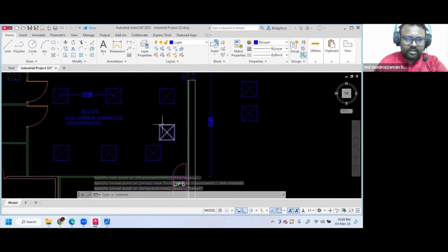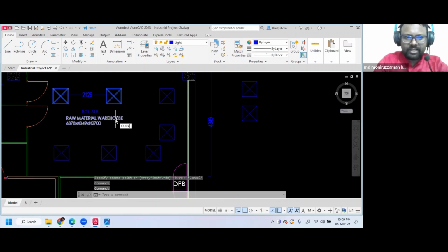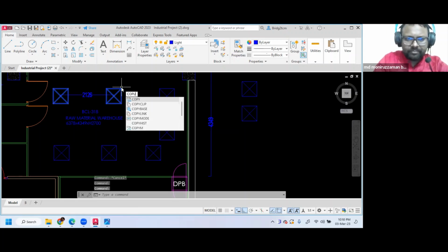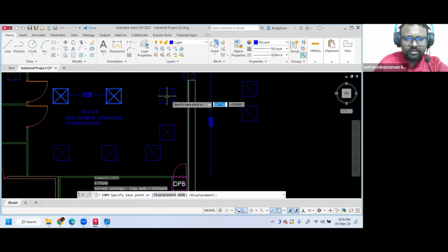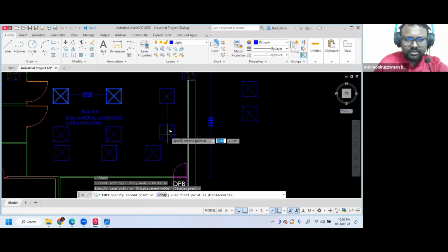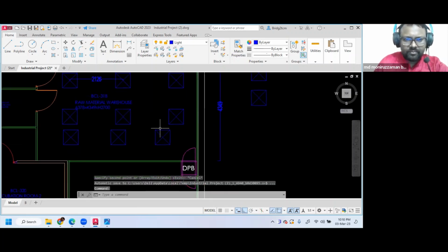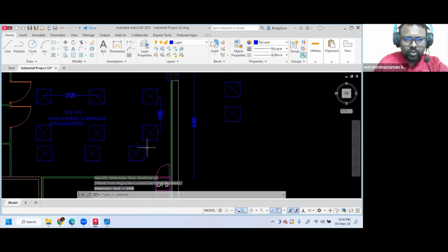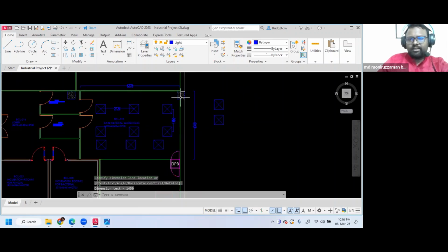Okay, and the other line will follow the same. So we'll copy the other line. First, we select the lights. How to select the lights? Click, it is selected. Click, the other one is selected. Done. Copy. I'm doing the copy by command. Take the reference, put it in here. What is the difference in between these two? 1450. 1/3 of the room width.